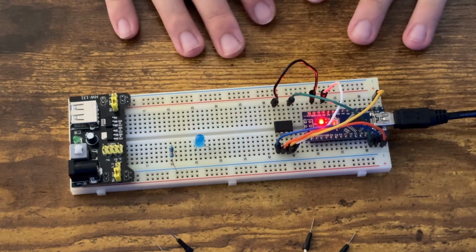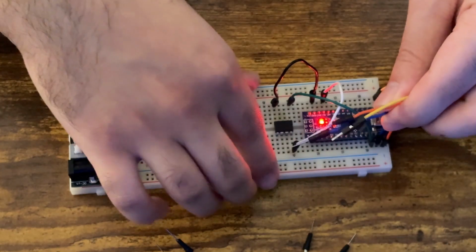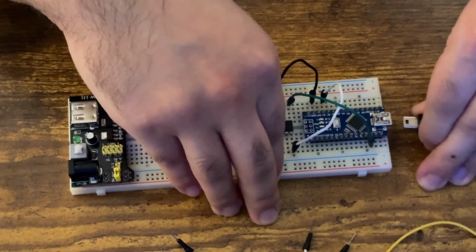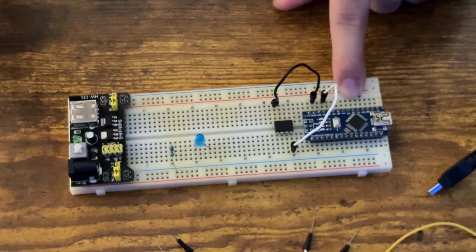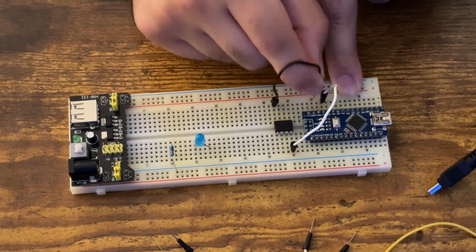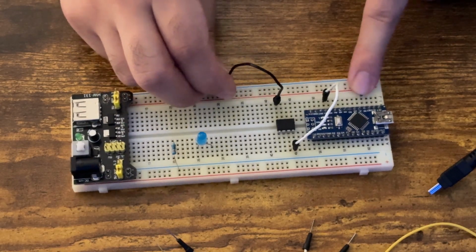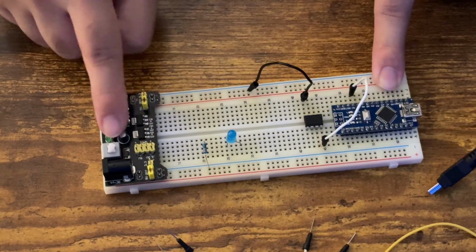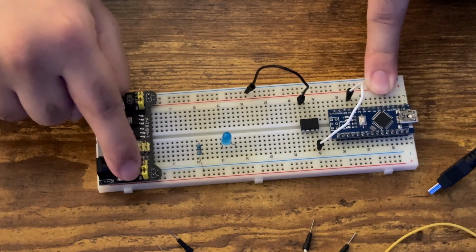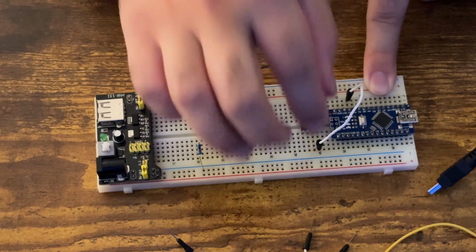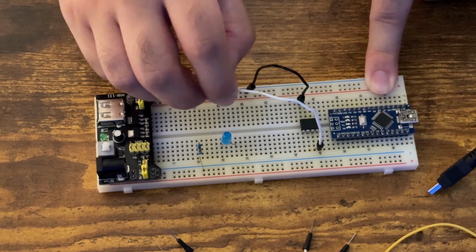Okay, so how do we test this? First of all, of course, we need to remove all the wires from Arduino. And actually I should have unplugged Arduino first to unplug power. So these wires are gone. Now we need to connect ATtiny to external power. So here I have this board that provides power from USB, and I can choose either 5 volts or 3.3 volts. We'll use 5 volts because this is what it was in the datasheet, I think, of ATtiny 85.